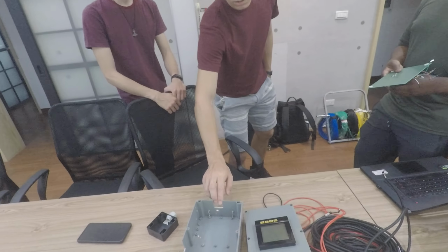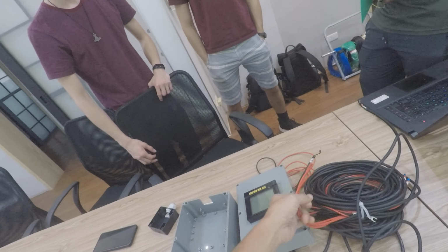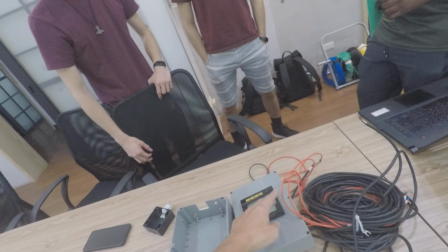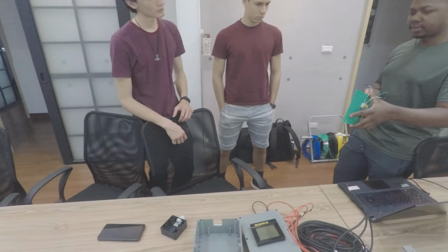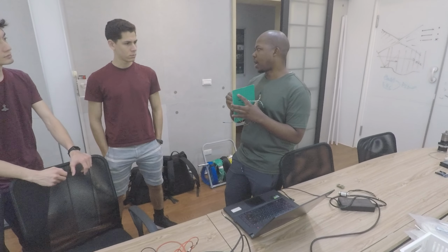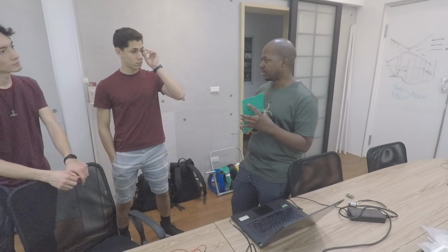Do you know what's the disadvantage of this? Because the edge is too sharp, it's very easy to damage the cable. There's also the problem that this allows dust and moisture inside of your enclosure. Imagine you have your printed circuit board and your tracks, which are basically conductors.